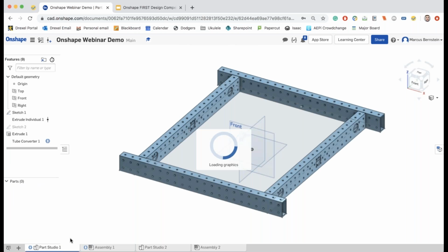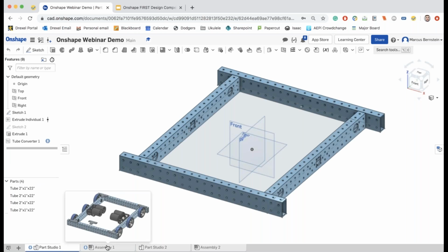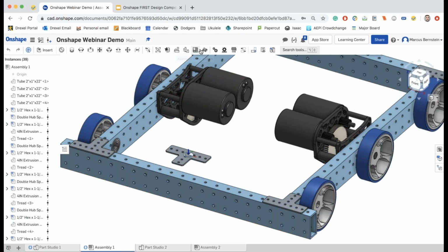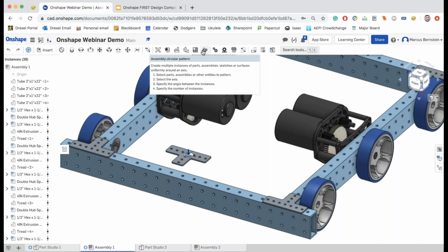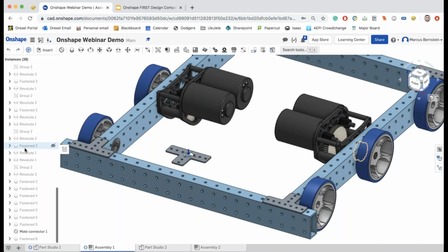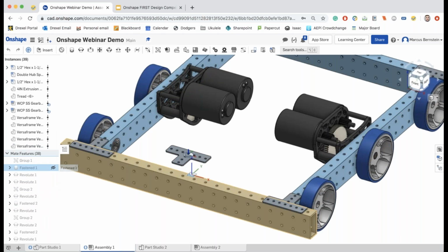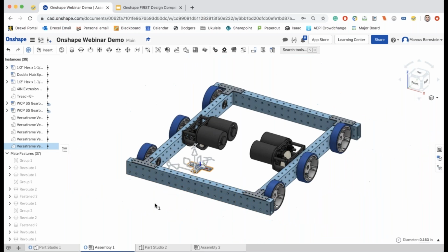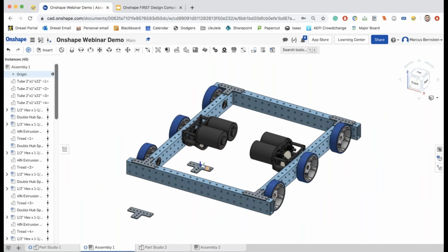The first way to do it is you can use an assembly circular pattern to almost pull it off. I'll show an example. Say I delete my initial fasten made to the origin. I'm going to make a copy of this as just a dummy part, and we can get rid of it later. Now I'm going to make the origin visible again.